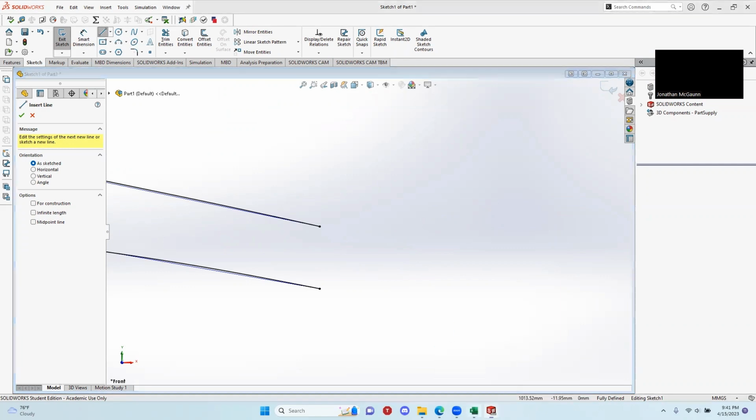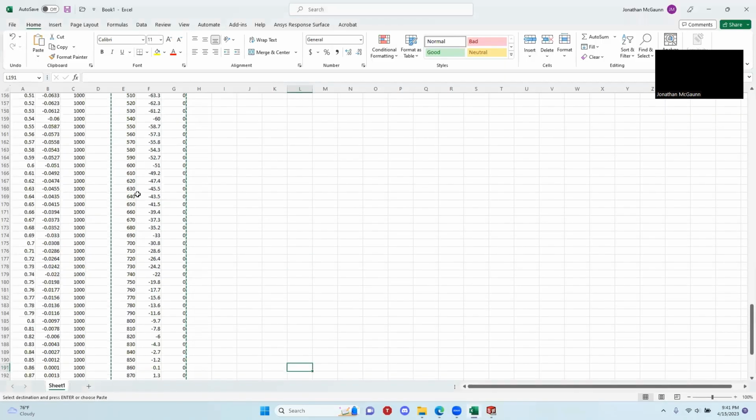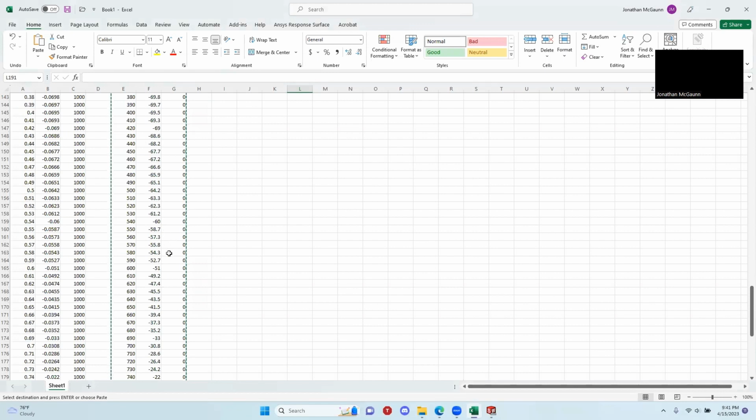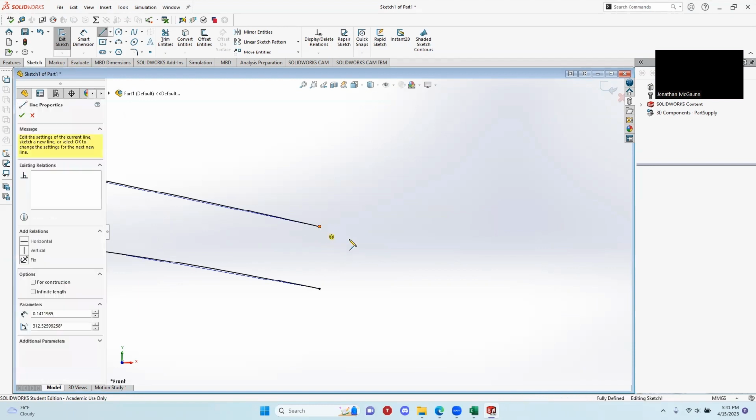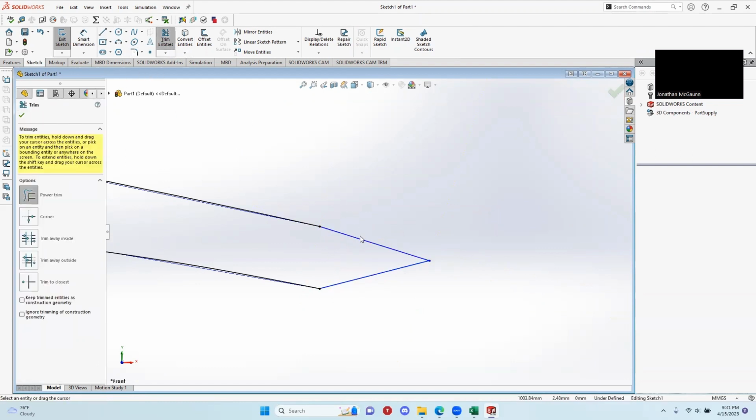So in the event you wanted to do that, you can manipulate your coordinates a little bit and create a zero thickness trailing edge. Again, that's kind of like a trial and error type thing. Or you could technically just extend things out a little bit and maybe add a fillet to these edges to make it a little bit easier and a smooth transition.